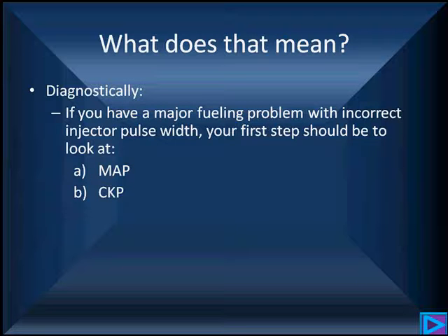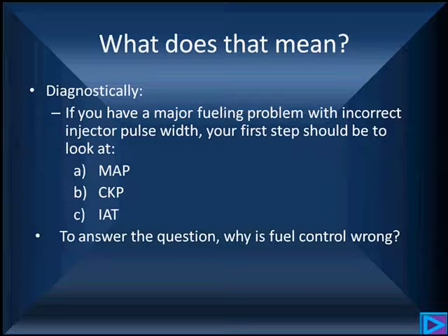Do we have a good clean crankshaft position sensor? Inlet air temperature, does it look right? You need to answer the question, why is fuel control wrong? Now let's stop and think about this. We have a dividing line. I'm going to talk about it here.